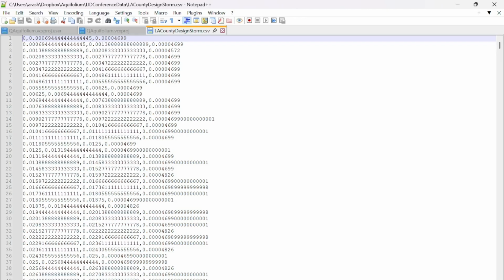So this is how it works. Look at this. It has too many digits, so it may be a little confusing. Basically it has three columns. You can label them too. OpenHydroQual is not going to read your label. So it would have been wiser for me to put some labels to make things clear. This is very raw. But what it is: the start time, the end time, and how much it rained in between those time bins, okay? And they don't have to be uniform. They don't have to be structured, right? So you can have, I don't know, this much rain in this 1 hour, and then the next 2 hours, this much rain, and then this half hour after that, it rained this much.